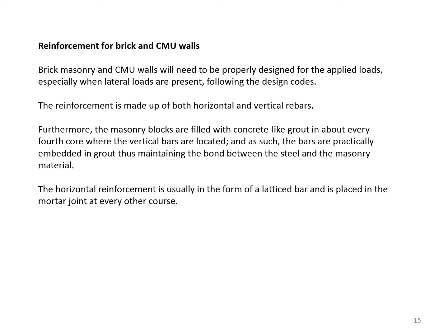The horizontal reinforcement is usually in the form of a lattice bar and is placed in the mortar joint at every other course.